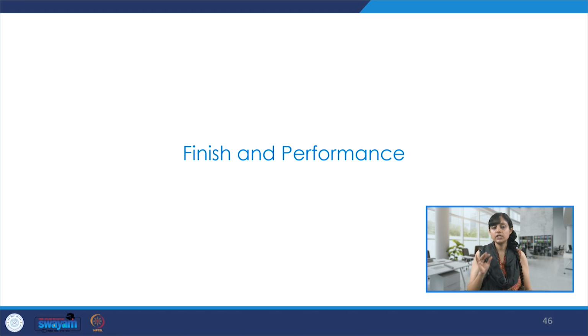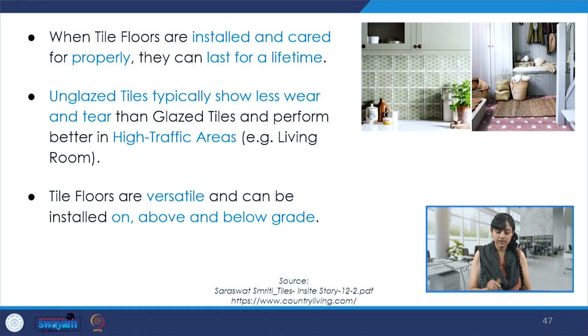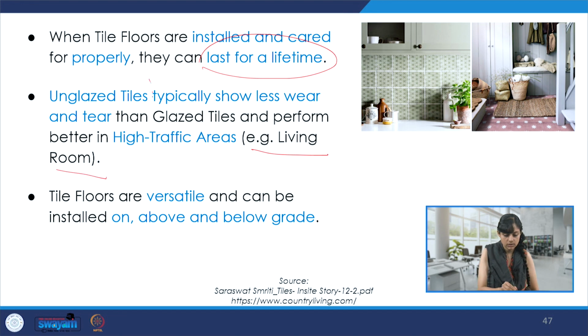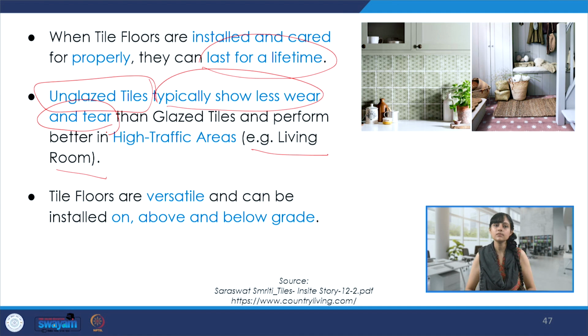Now talking about the finish and performance when we are doing tiling. When tile floors are installed and cared for properly, they can really last for a lifetime. And unglazed tiles typically show less wear and tear than the glazed ones. And they perform better, the unglazed ones, in high traffic areas, for example, the living room. So the unglazed ones typically show less wear and tear. And tile floors are versatile and they can be installed on, above, and below any grade.